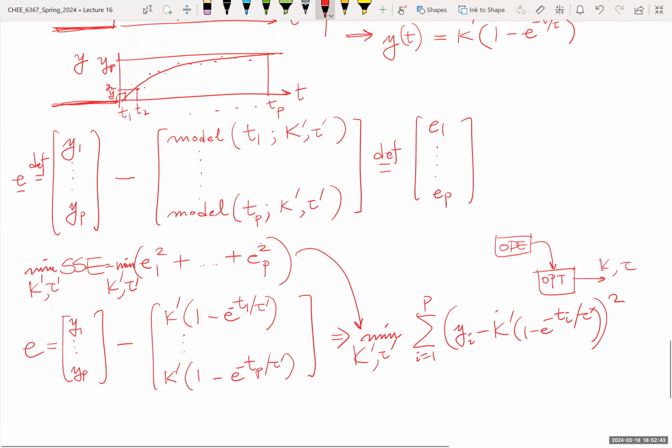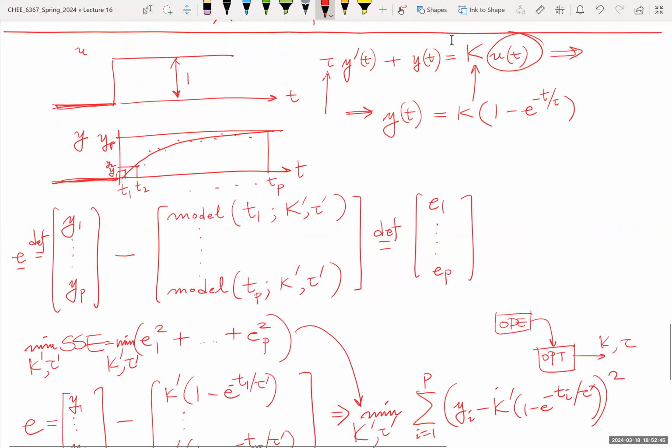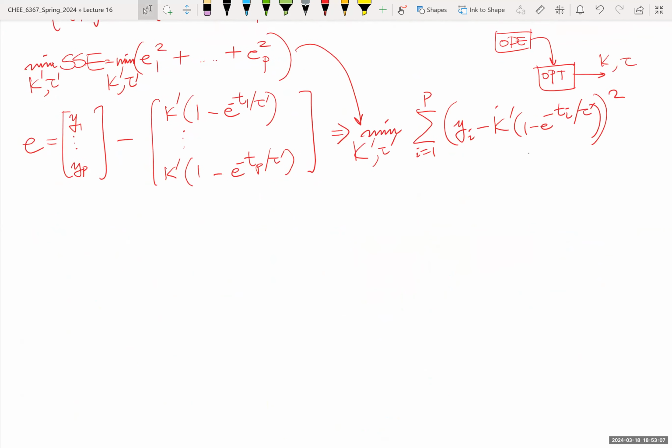So when we have an equation that is solvable and it gives us a nonlinear regression problem to solve, to estimate k and tau, it can actually be looked upon in a different way. First of all, if we have problems like this, we typically identify models by taking a computerized version of the problem, which means discrete time.